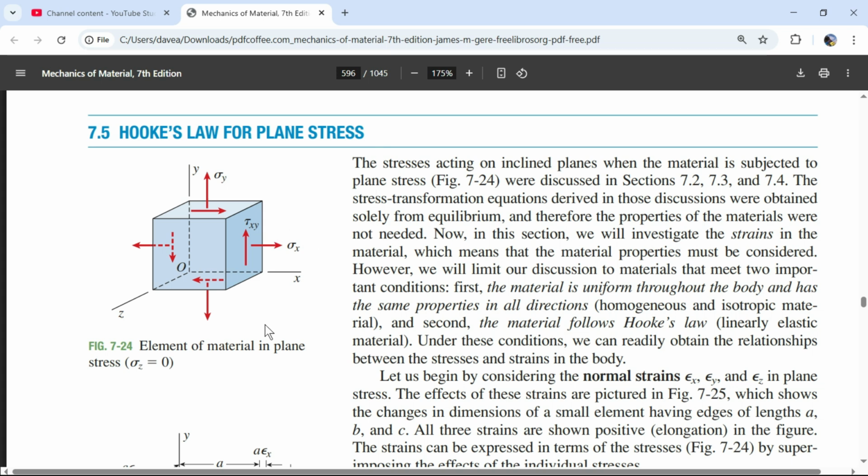Cool. Yeah, I guess you still have to throw an asterisk on the shear stress, because if you take the cut here or in the middle or down here or somewhere in between, this shear stress is for sure going to vary. Check this out though. If we just have biaxial forces, we do not on a cut like this. Yeah, so let's do that.